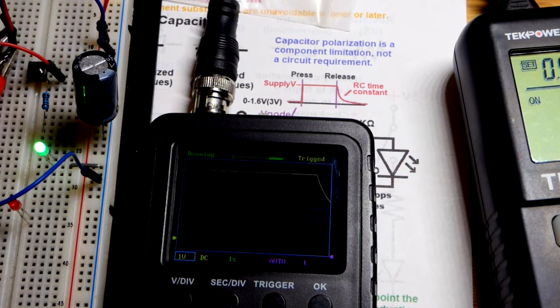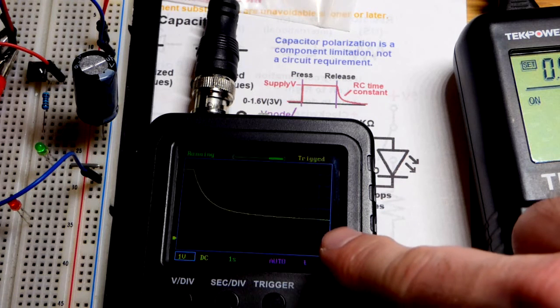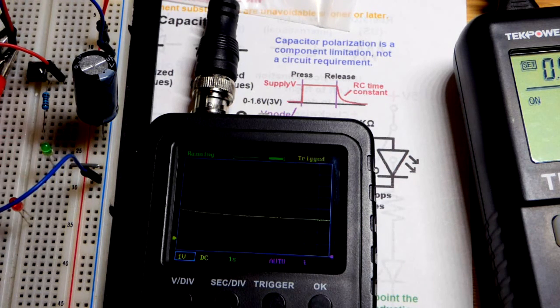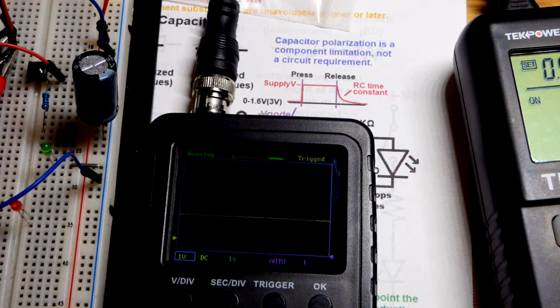Now when I let go, you can see that the curve goes slow. But it's still the same curve. And you also notice here, it is not going right to 0 volts. That's 1, 2 volts. These LEDs block voltage even while they're forward biased, even while they are set to conduct. And so at lower currents it goes down a little bit, but there you can see it's pretty leveled off. It's not down to nothing.